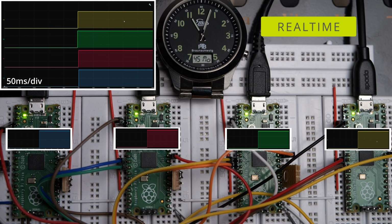In order to demonstrate the effect of clock drift over time, we set up a demonstrator using 4 Raspberry Pi Pico boards. All Picos contain identical software, which turns the onboard LED on and off at fixed timer values. On the top left is the output from a logic analyzer, which shows the LED signals. Each Pico has its own crystal that drives the timer. The total recording time was over 30 hours, small parts of which will be shown in real time and slow motion.